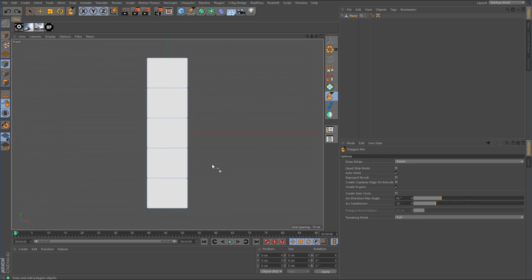So right now this is 1-to-1, and what I mean by that is up at the top we have one face and we want to try to reduce it down to 1 at the bottom. Of course right now there's nothing to reduce here because it's 1-to-1, so there's nothing to do. But if I were to take this top face and split it in half, now we have two quads. So now this is 2-to-1. That means we have two quads that we need to reduce down to 1. And we should be able to do this here in the second face.